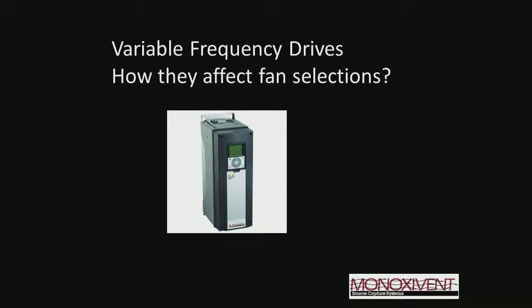Now, we get more and more requests for these every day, especially from the colder climates and the real hot climates, that people are asking for variable frequency drives. In our opinion, they tend to look good on paper, but when you really look at what has to be done, you need to pay attention to not only the fan selection, but your duct layout if you want to use a VFD and have it be effective and have it work properly.